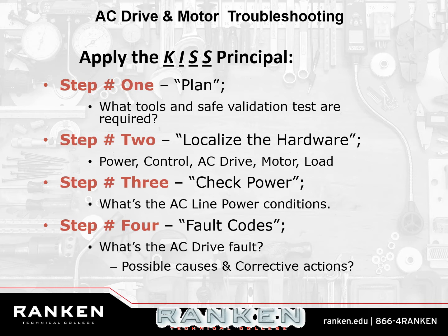The other thing you need to figure out is what you're going to have to test in order to make this thing work. So, second thing is to localize the hardware. Localizing the hardware means that you figure out where the power is coming from, what's controlling it, where the drive is, and where the motor is, and what is the motor doing. Sometimes it can just be as simple as there's a blown fuse, and fuses blow, and you pop them back in, and they never blow again for another 20 years. Sometimes it's more complicated than that. Don't make it any more complicated than it needs to be.